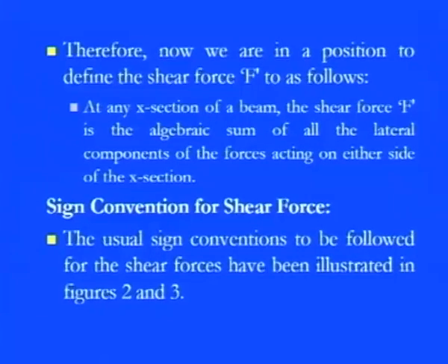Even if you divide this beam into many cross sections, many segments, and you take the shearing force at one segment by the application of force, simply sum up those forces linearly, and you will get the overall impact of these shearing forces on the beam. So we are saying this is the algebraic sum, that means it is a linear sum of these forces, because they are applied all across the beam, and since we have the same cross section of a beam, they are set up in this beam in a very uniform way.